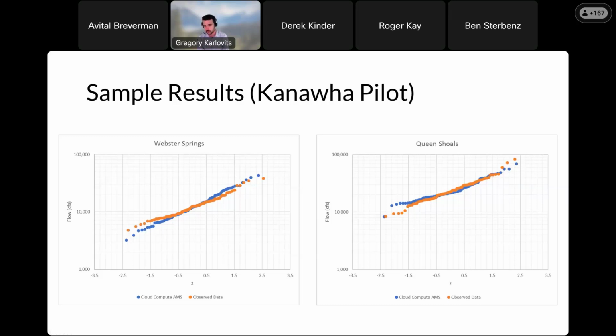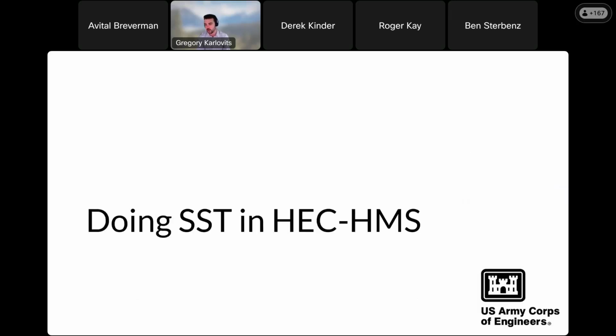All the calibration for these flow frequency results are in the HMS model to get our excess precip correct, and then in the RAS-2D models to make sure that our runoff response and the timing and all of the shapes of those hydrographs are correct. So the meteorology in this case, which absolutely dominates the estimate of the hazard, is doing an excellent job of helping us get to these hazard estimates. So that's all well and good.